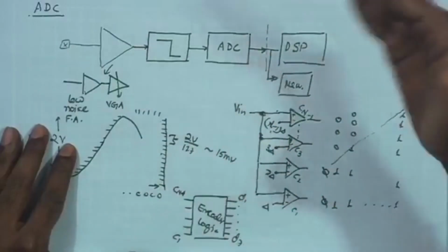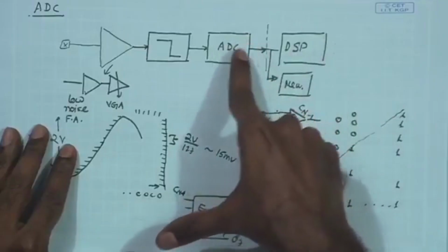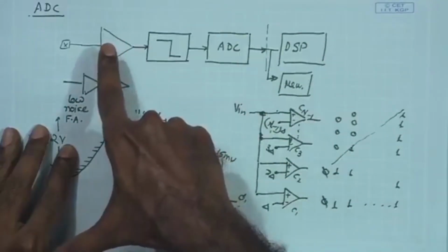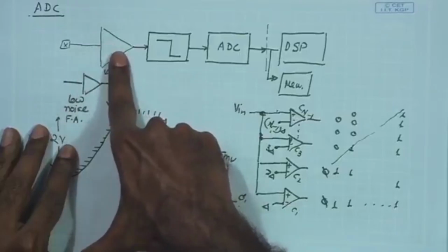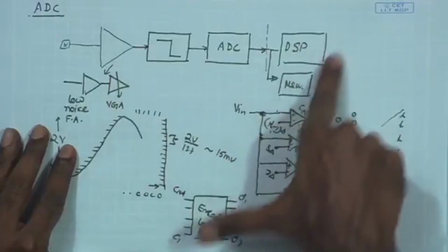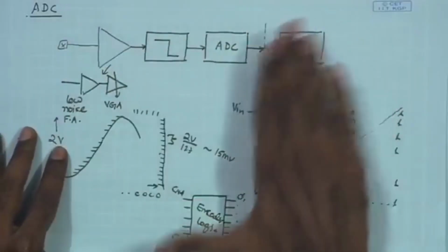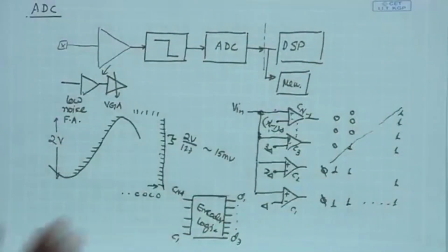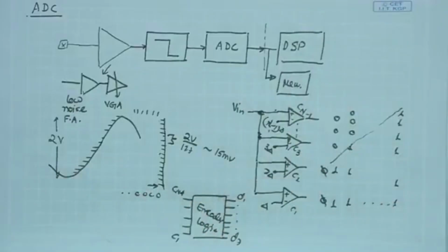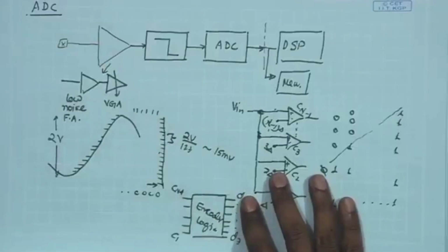If you are trying to implement some algorithm in the digital domain, that will tell you how many bits of precision the ADC must have, and correspondingly how much resolution and accuracy the analog domain processing must preserve, so that the required information can be extracted in the digital domain. That information comes from established studies which tell us that 7 bit of precision is good enough for the data that we are targeting, and we also know the kind of frequency content that we have in our data.